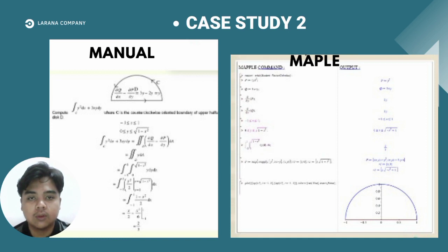And we go to the Maple solution. In the Maple command, we must write restart and with(student) and vector calculus to access this equation, because we cannot proceed if we didn't write vector calculus.